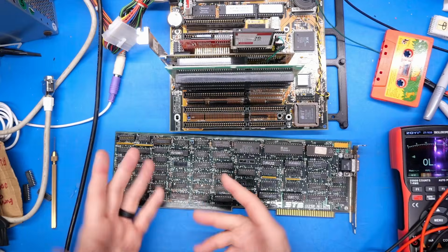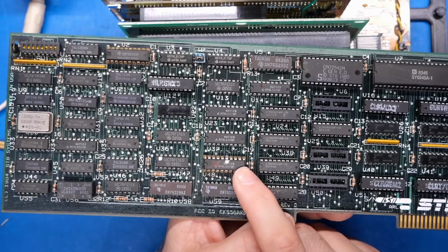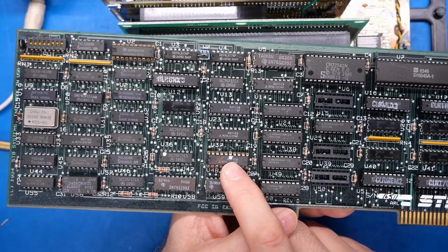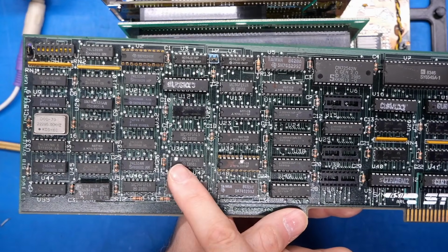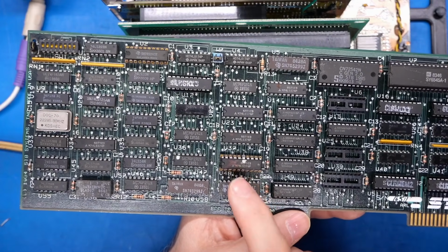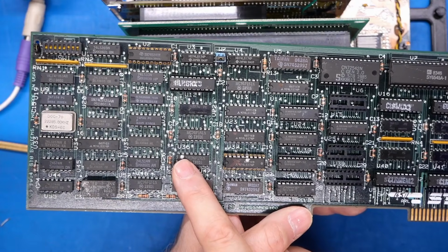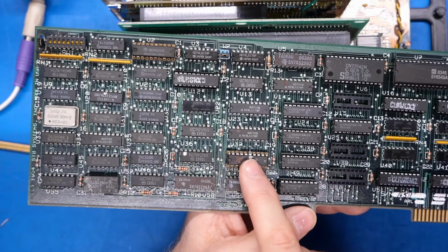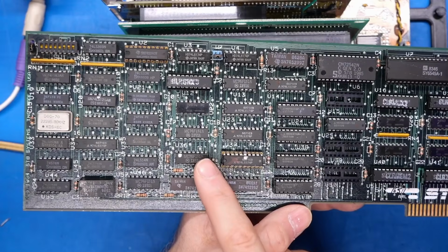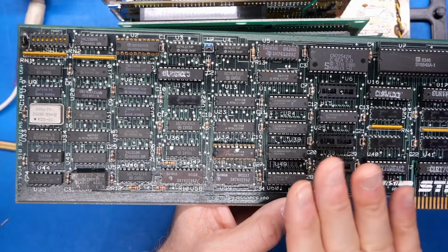Okay, I'm just gonna remove the entire chip. All right, I removed the chip, put it in a socket, and then I bent out the pin. So that pin, which goes to this chip, is no longer in play. So we can do two things. We can check the output of the pin here while this thing is running, and then we can also try to bring this pin up to 5 volts through a resistor and see if that's possible, and see if we get the attribute and that row of pixels or that column of pixels that we're expecting.